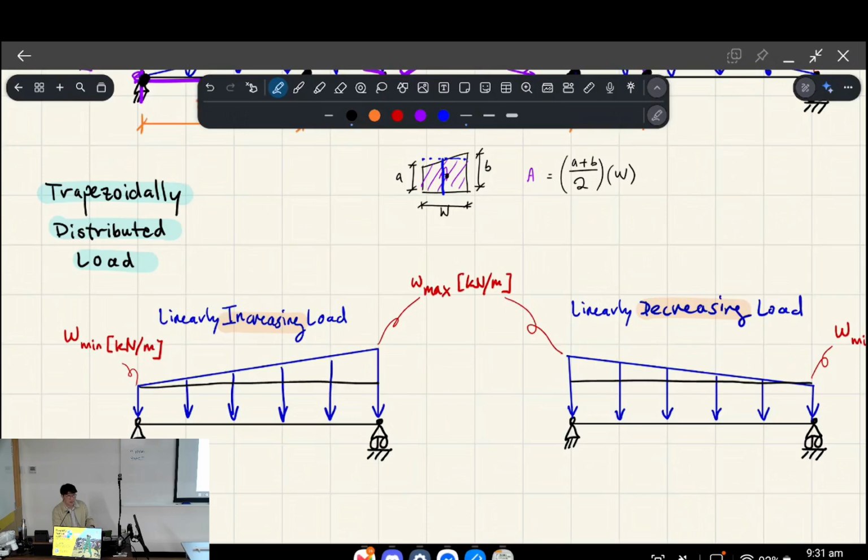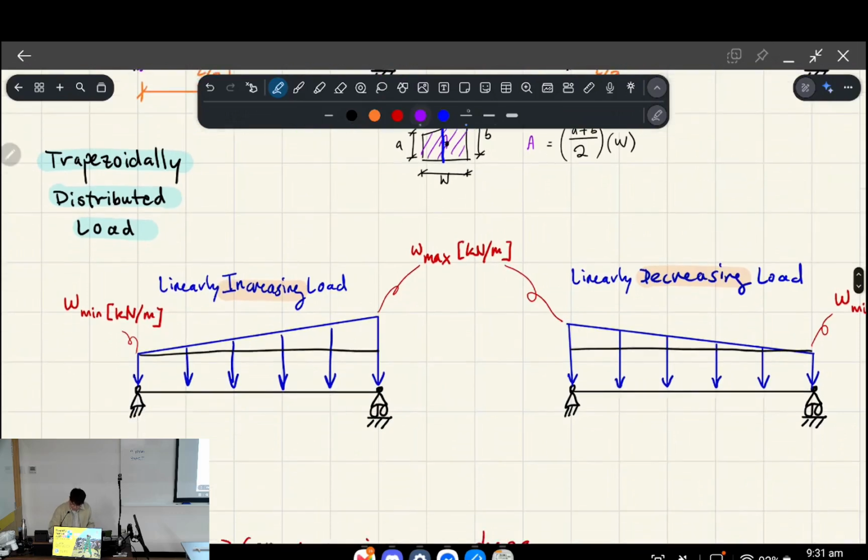So when you're doing the cumulative forces, or the equivalent point load, you might just want to do this, where you've got a rectangle, and we know from before a rectangle's centroid is in the middle, and then a triangle centroid is 2/3 from the small side. So that's one way you can deal with trapezoids.